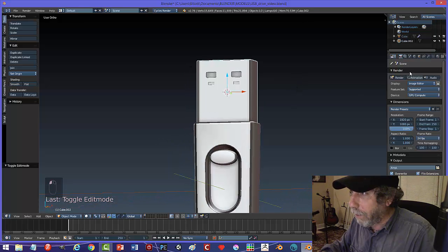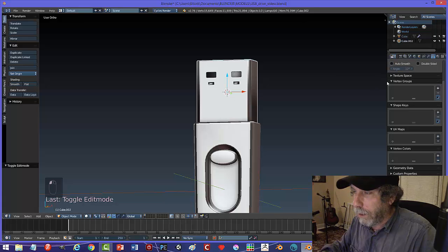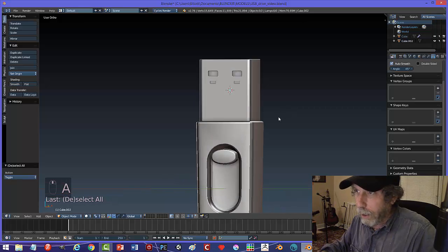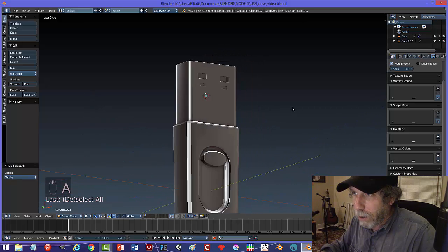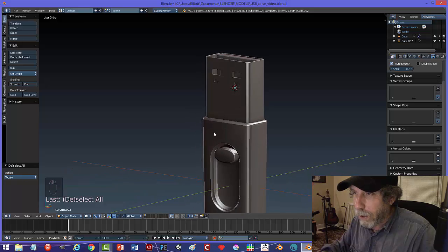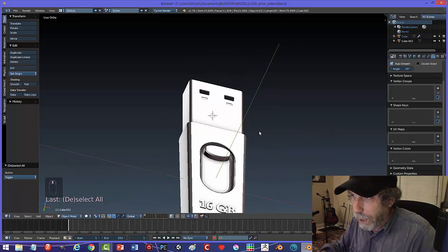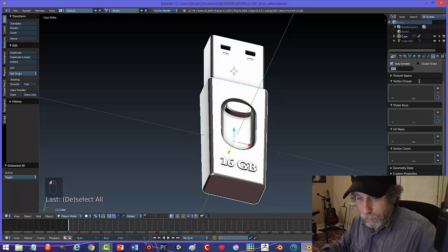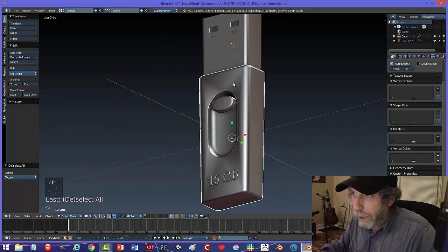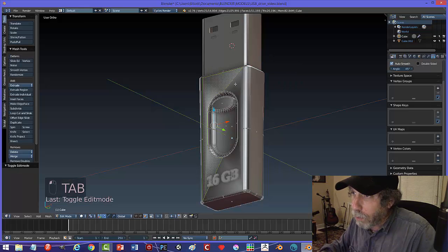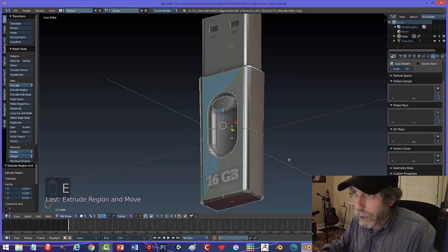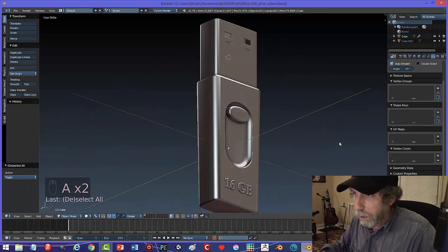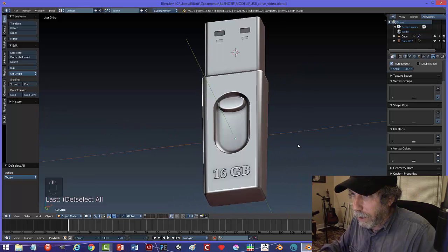And then you might be able to bump up now your smoothing. You know, let's try 45. And now the edges are really smooth, and we don't have that problem with that face. And I'm not sure if I'm having that issue with the front as well. If I was to bump this up to 45 right now, I get some of that. So let's see if this works. Okay, B, accept, come on out. All right, and that smooths it nicely.